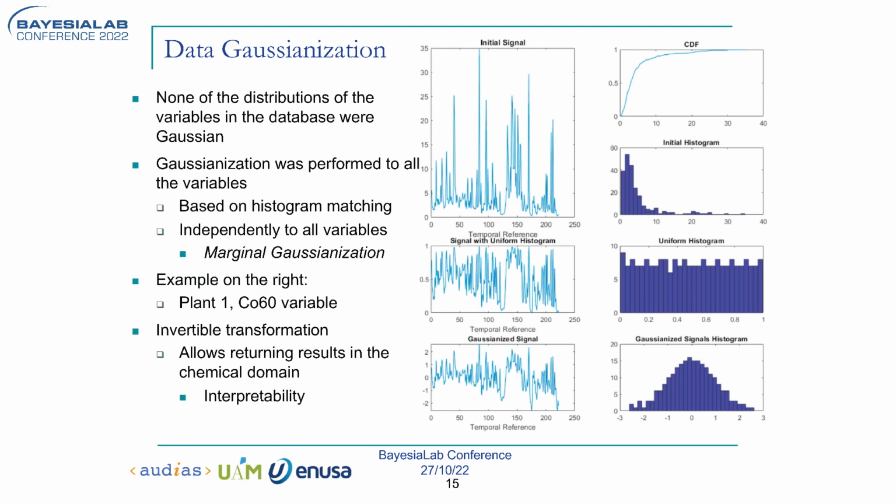So the Gaussianization works in the following way. You have the initial signal, compute the cumulative distribution function. We apply this function to the histogram, so we're inverting the distribution of this histogram. We obtain a uniform histogram. And if we apply an inverse Gaussian distribution, we obtain a Gaussianized system. Okay? This is how this works.